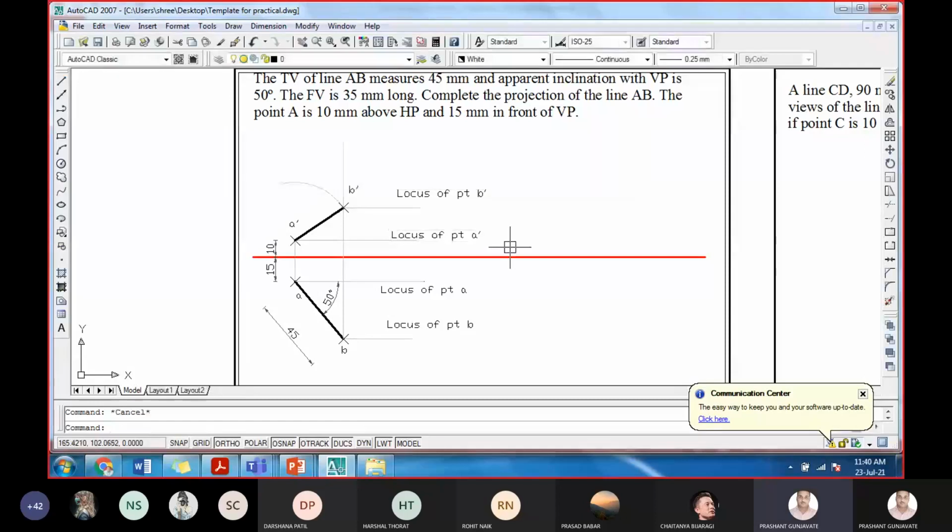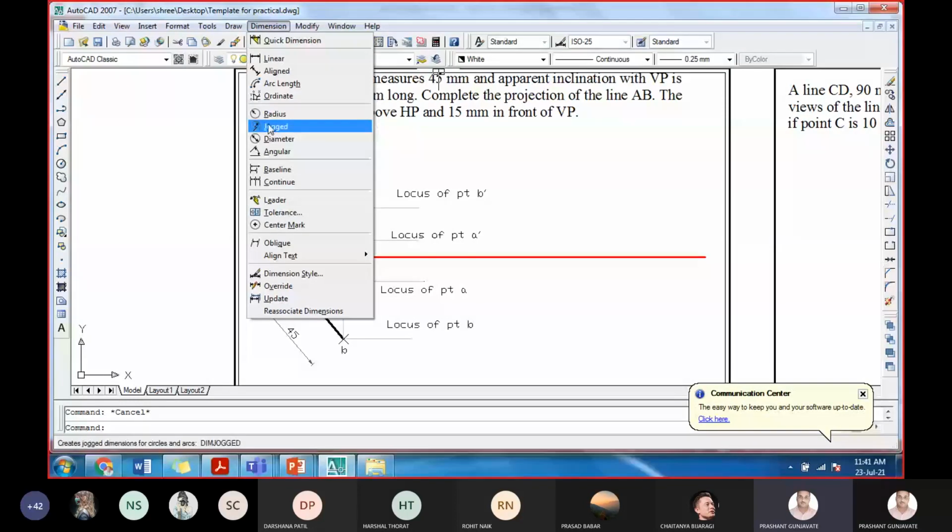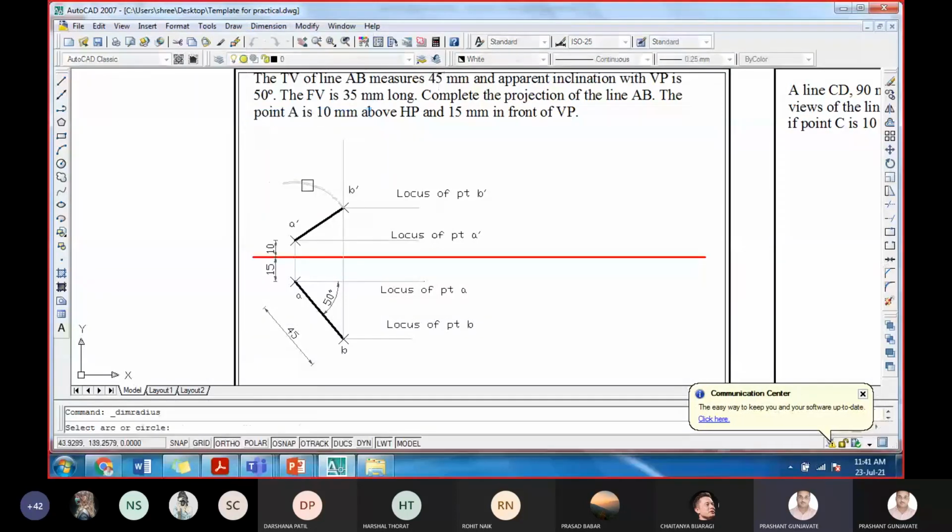Okay, now up to this, we are clear what is given. We have mentioned it here. Let me show the radius, that is R35. Apparently, what is the data we have? It is all about the apparent length. So what is next to do? What should we do next? Draw the true length.